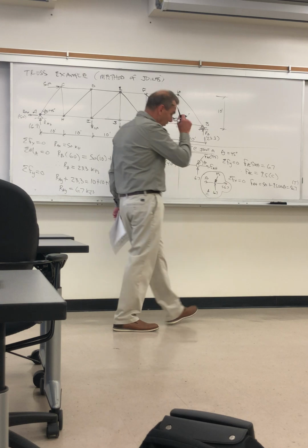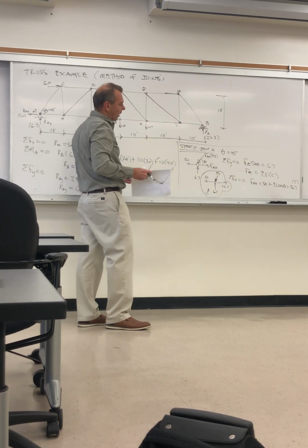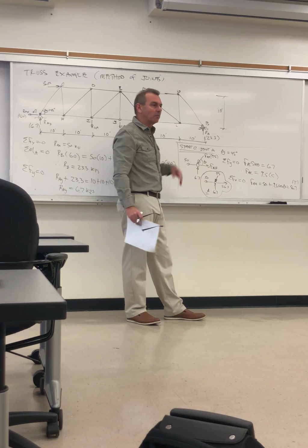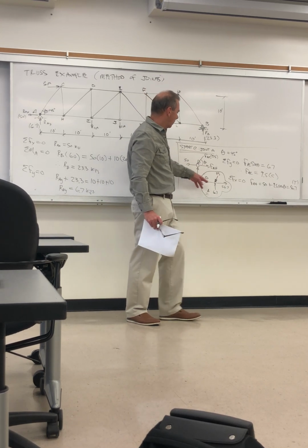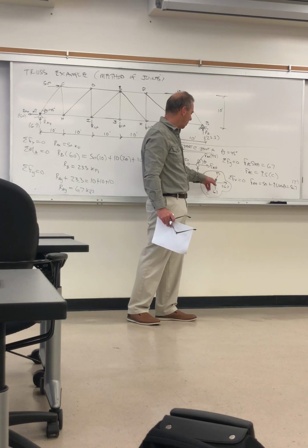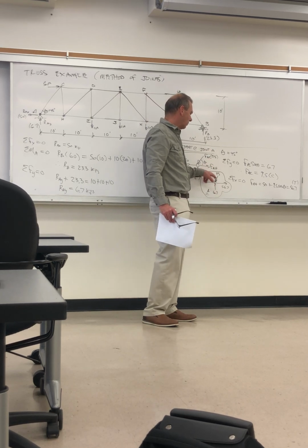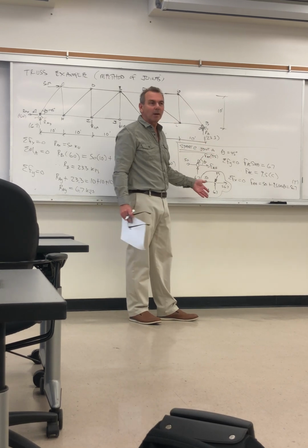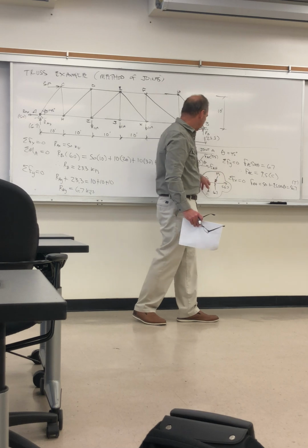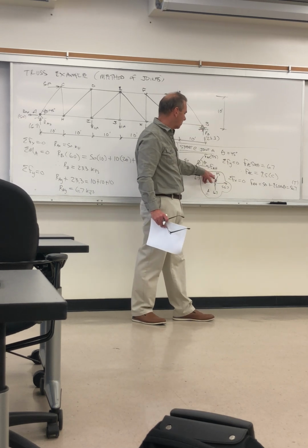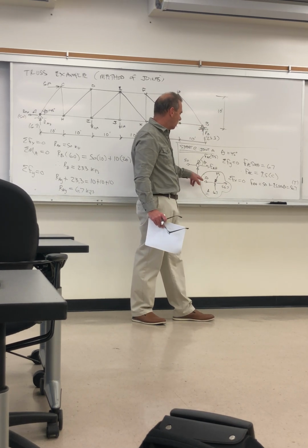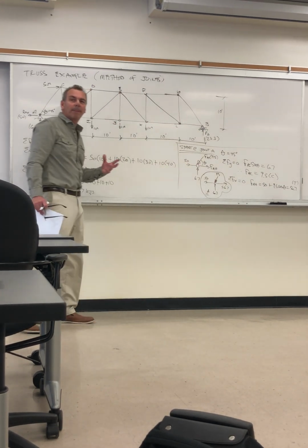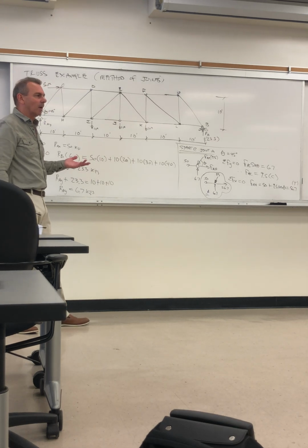Okay, so you can look at it, and without doing any calculations, just take a glance to make sure it looks balanced before you move on to the next joint. So vertically, you can see 6.7 up, a vertical 0.707 and 9.5 looks about like 6 or 7. So vertically, you can see it's balanced, right? Horizontally, we have 50 this way plus a little bit, 6 or 7 from 9.5. So that's 56, 57, and then to the right is 57. So 56.7. So you can see just looking, glancing at it, it's balanced.